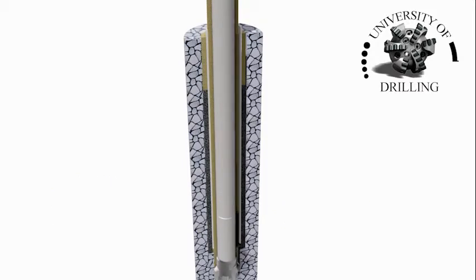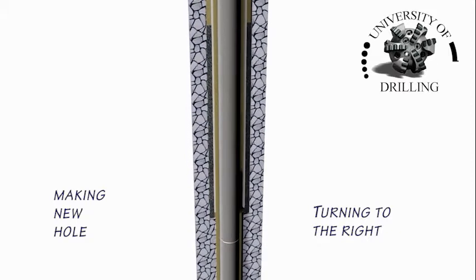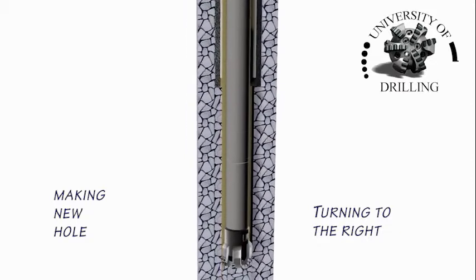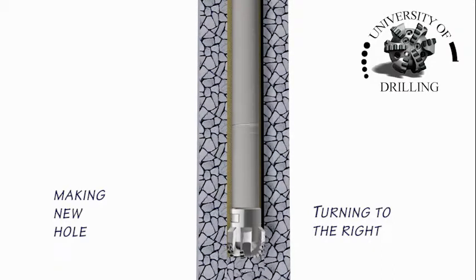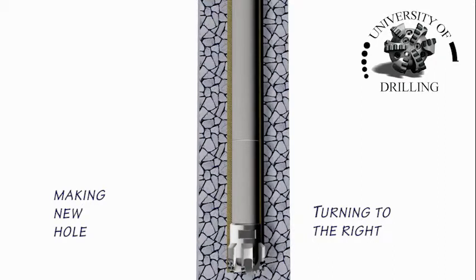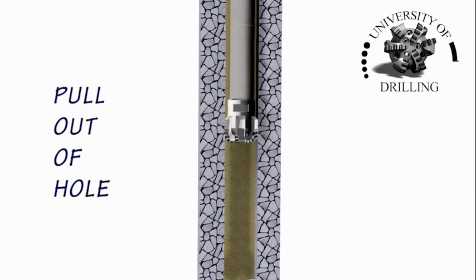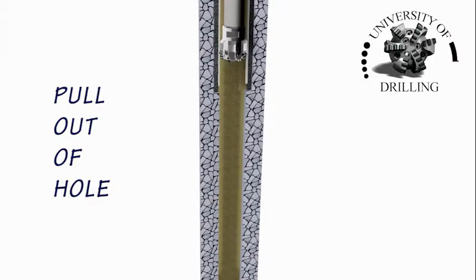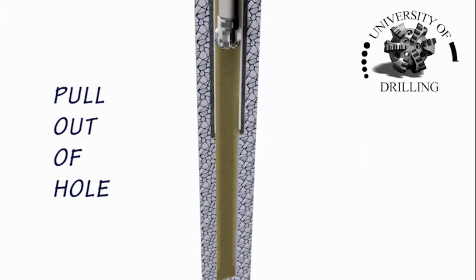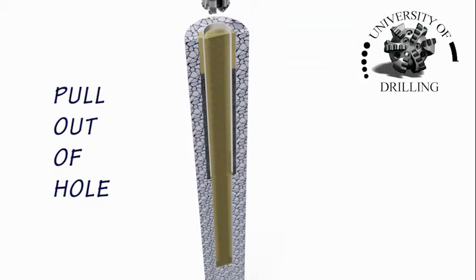After drilling the casing shoe track, drilling new hole can continue to the next hole section total depth, or TD, where cuttings will be circulated out of the hole to prevent the cuttings from interfering with running the casing in the hole and cementing the casing annulus. The process of pulling the drill string out of the hole and using the mud to hold pressure on the borehole until the casing can be run in and cemented is repeated.